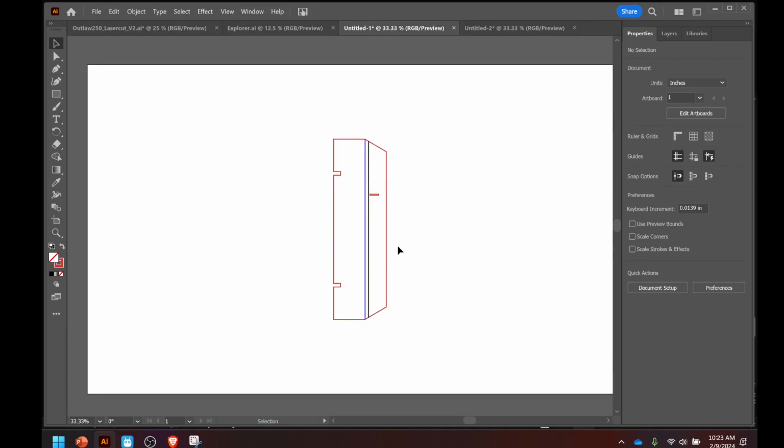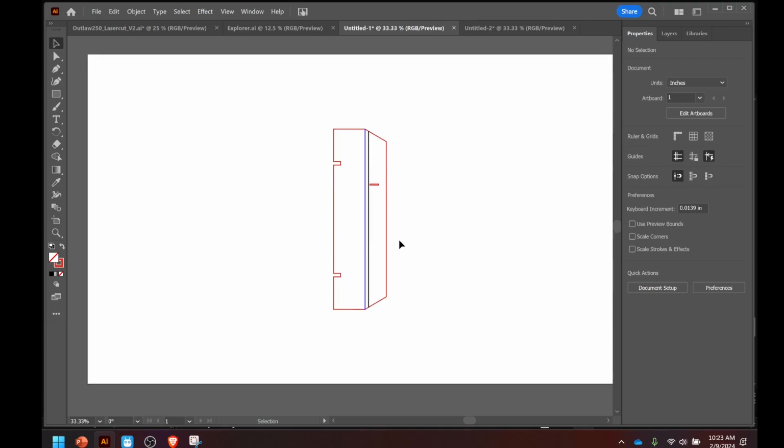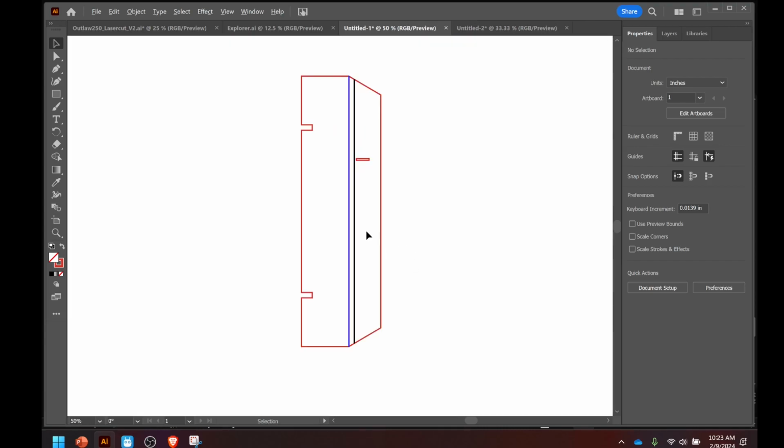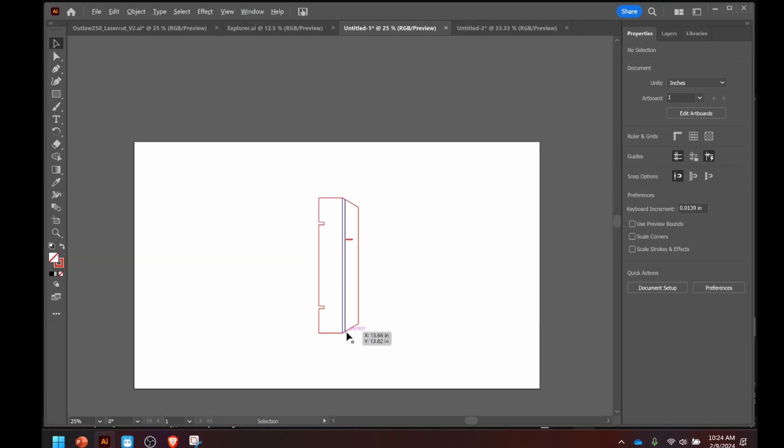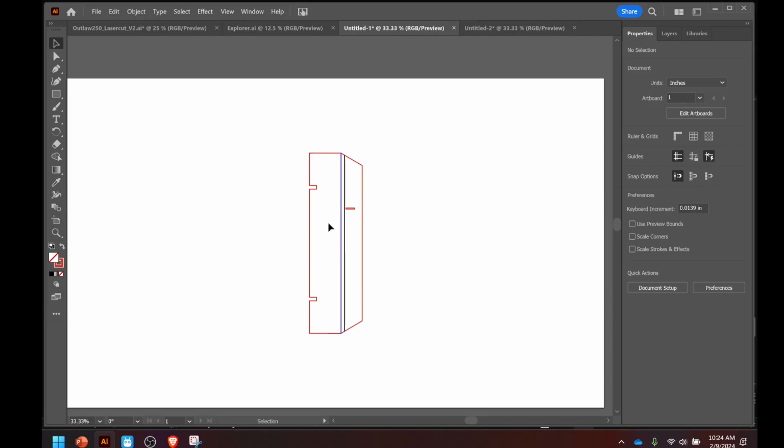We want to change the shape of the elevator or change the size of the elevator. Now this one has to fit in to those two vertical stabilizers on the Outlaw. If you think about the plane itself, it has to fit in there. So we can't adjust these little cutouts very much. They have to stay the same, but we can change the size of the rest of the elevator. Let's say we want to make the elevator wider, in this up and down direction, we'll say. So let's try and see what happens.